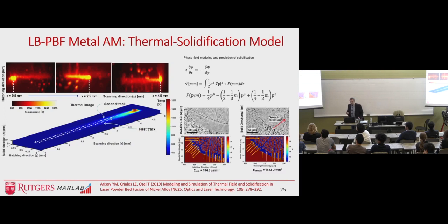Let's get to the thermal solidification model. In this case, we use, again, MATLAB, and we wrote our own code. This time, we solved the heat equation in 3 dimensions, and then we get a 3-dimensional solution for multiple tracks. And then we validate the simulation results with the thermal images. And then we use a phase field method to predict the nucleation or solidification along the melt pool boundaries.